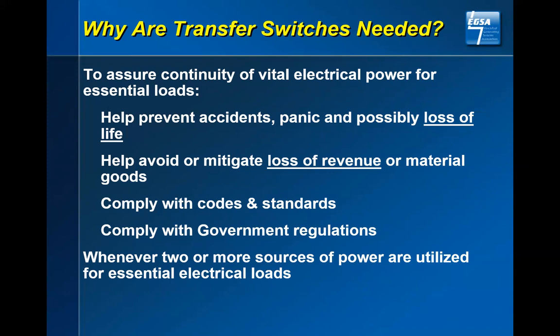Whenever two or more sources of power are utilized for essential electric loads. You know, that's almost a misconception now, because you think of backup power, and backup power is for things like hospitals, arenas, data centers. But I don't know that you can go into any facility now that does not require backup power. One of the ones down here in the hurricane prone area are grocery stores. If a grocery store loses power, number one, obviously food spoils, but number two, you can't even get through the registers.